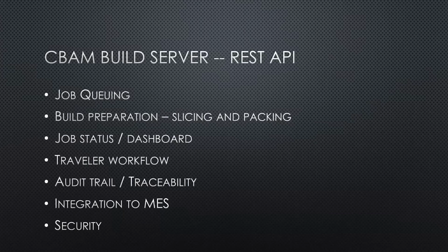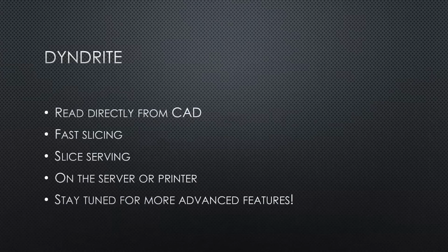Now, one question is, why are we at the Dyndrite meeting here? So let's talk about that for a second. We've been working with Dyndrite on integrating their kernel into our build server here. That allows us to read directly from CAD data, do fast slicing and slice serving. This could be on the server or within the printer. It's nice, it runs on a GPU, which is very inexpensive, and it takes the CPU load off of the main processor, allowing us to put it on the printer if we want.